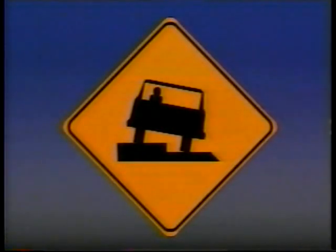Place a wedge of material along the face of the drop-off. The wedge should consist of a stable material placed at a slope of 3:1 or flatter. Put drop-off warning signs in advance and throughout the drop-off treatment. Place channelizing devices along the traffic side of the hazard 1 meter from the travel lane.